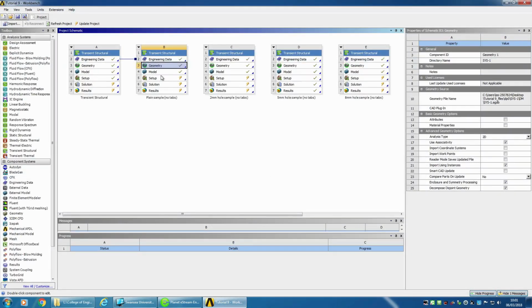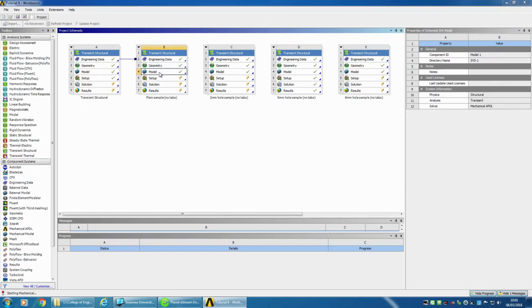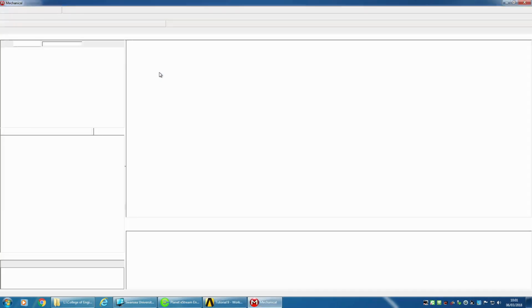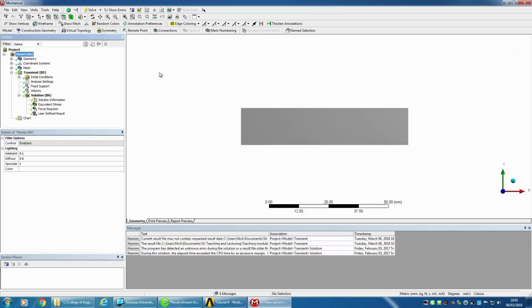We've done that many times before. And then we'll go into the model. So now we need to have a little think about what we're doing here, because we're actually going to put on some boundary conditions that aren't ideal. And you need to understand that these boundary conditions are not ideal. So this is always the trick when you subdivide a more complex geometry and model, and you take it down to a smaller section. It's always the boundary conditions that are going to give you problems.